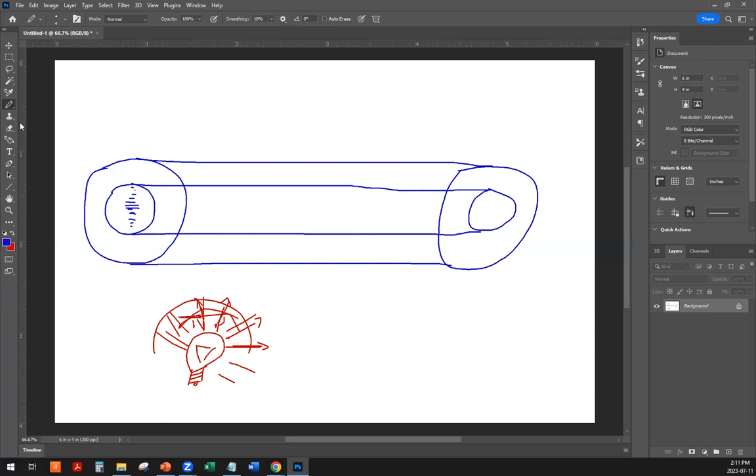So what happens now? We got a light beam. The whole point is to slow down, because we can't speed up the light in this environment, but we can slow the fastest one down, to accommodate the travel time that the other ones have to cover. So in this case, here would be the straight one, the beam of light, or the ray of light, or the mode traveling through the center.